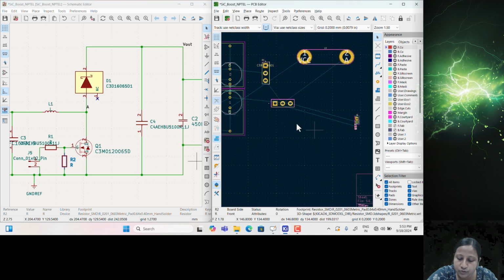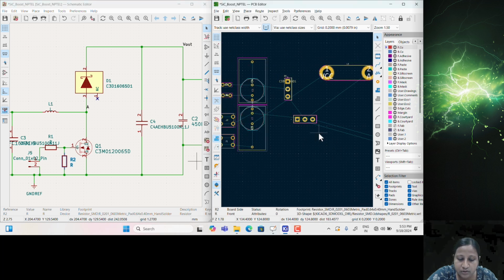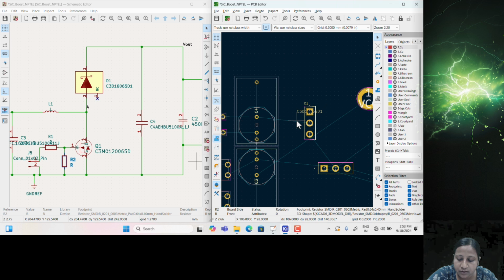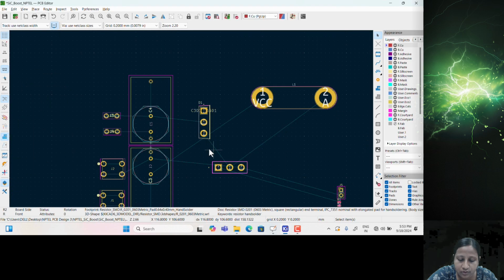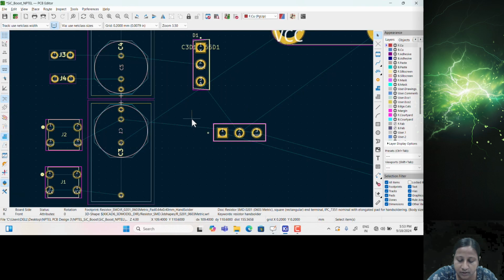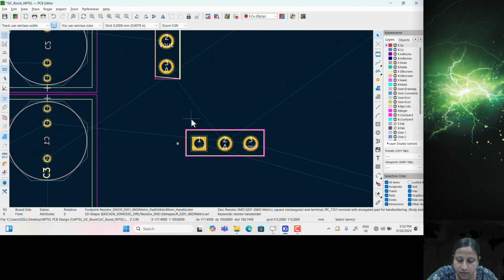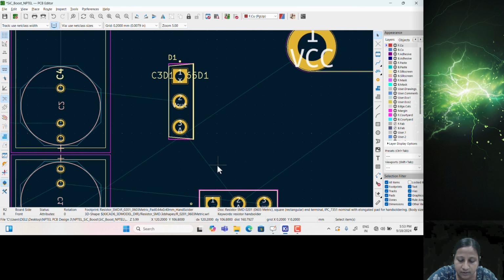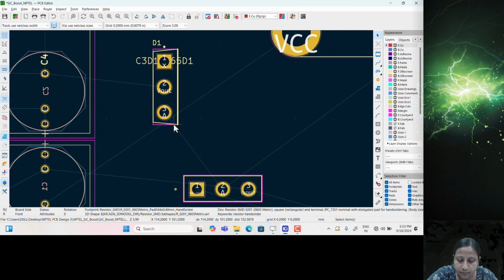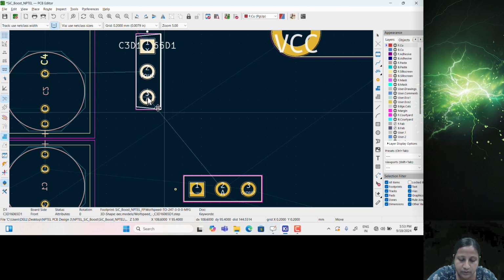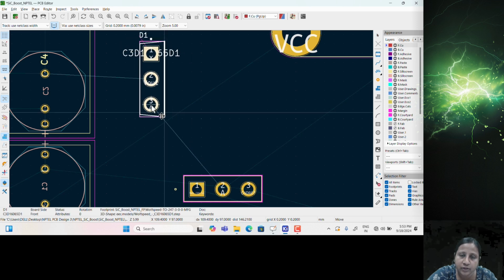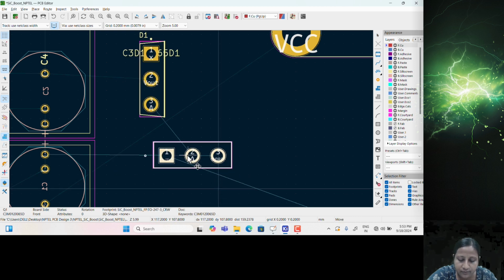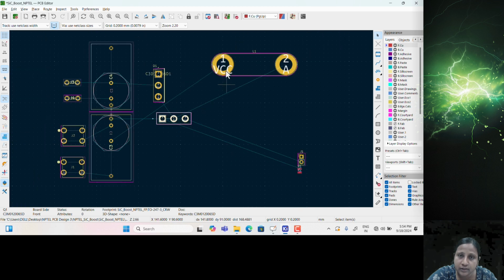You can also choose SMD for the main components, different devices, or the capacitors connected in the power board itself, but at this moment we haven't selected that. It will be easier to connect through-hole components rather than SMD components. For resistors it will not make much difference, because the connection may not be that difficult.